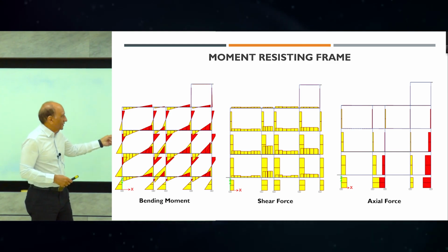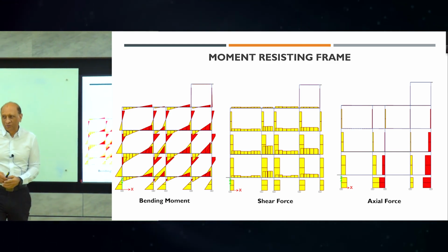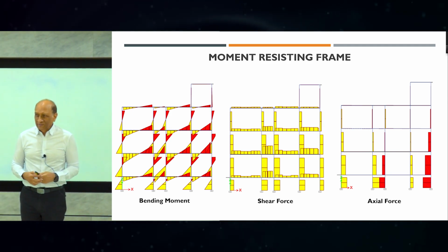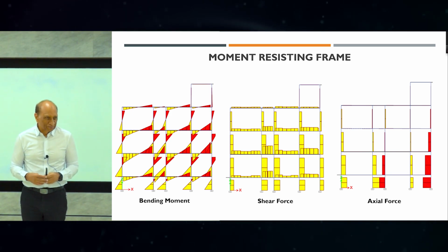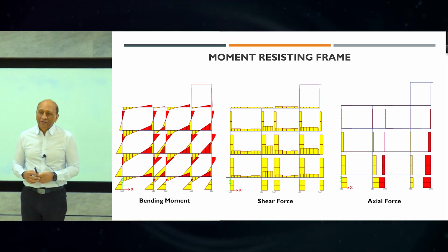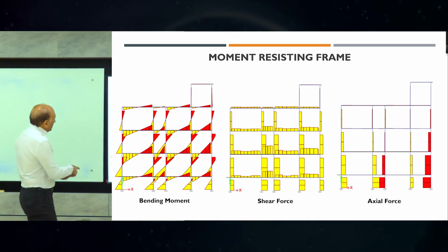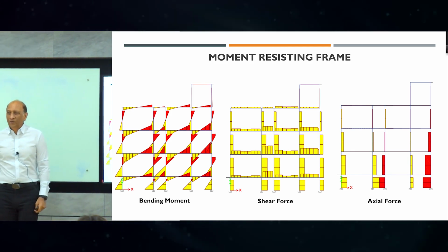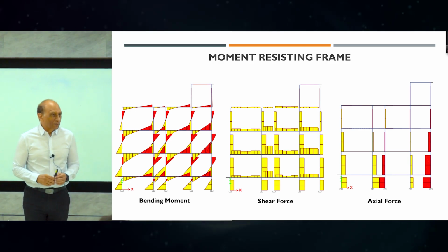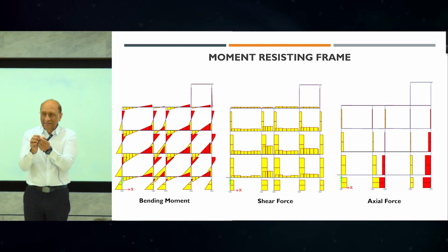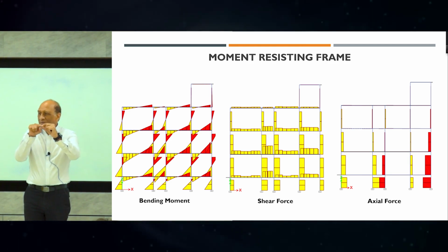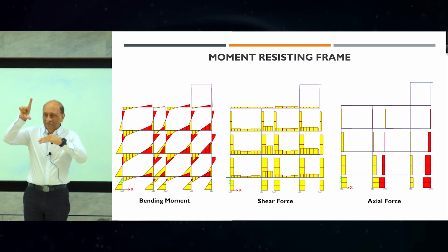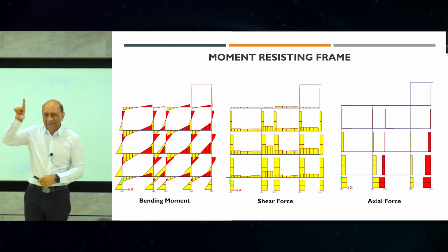The first time I tried to do a building like this one, it was not that high, 7, 8 stories, without computers, without anything, and I tried to figure out how to calculate all the bending moments in the frame. So we used to have what we call the cantilever method. Basically, you can see the observation from here that at the center of every column, the moment is zero. That's a very interesting observation. You can start with that idea that at the center of each column, the moment is zero. So you can apply a force at that location and calculate the bending moment from half the column height. And from there, everything can start.